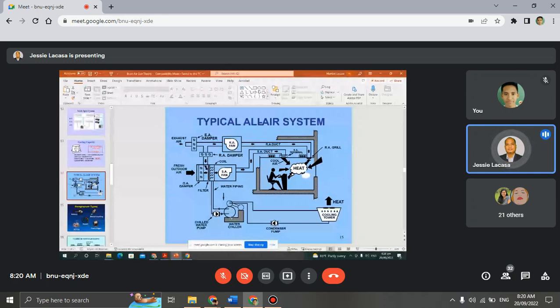This is your air handling unit. Heat exchange happens here, because there is air blown across it. The heat exchange happens at your cooling coil, which absorbs the heat from the air. Then the water returns again, and the cycle continues. That is what happens.